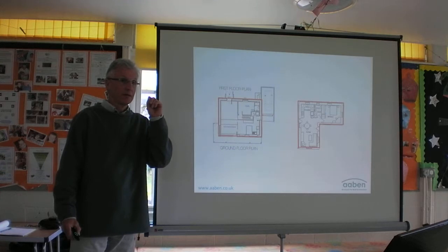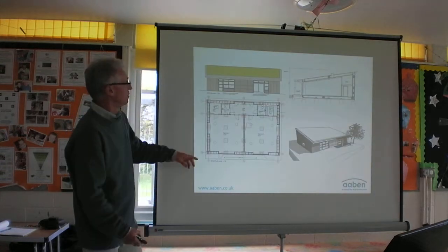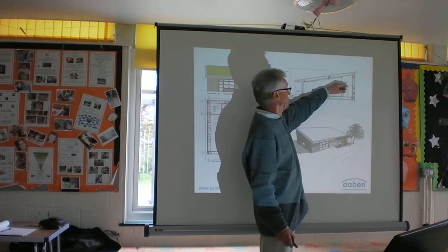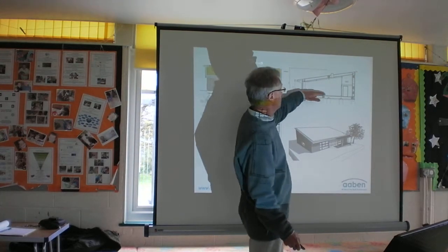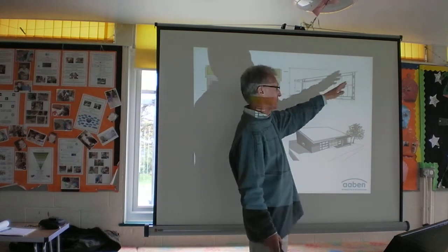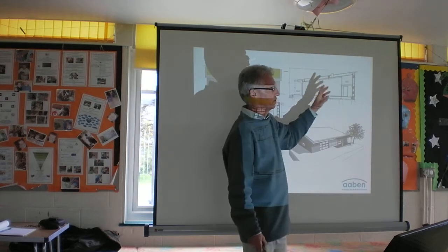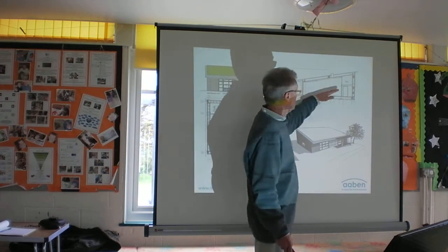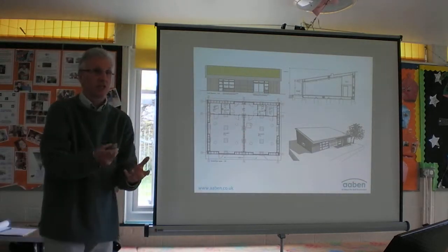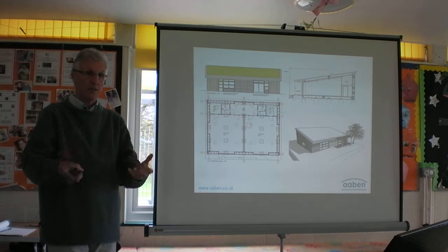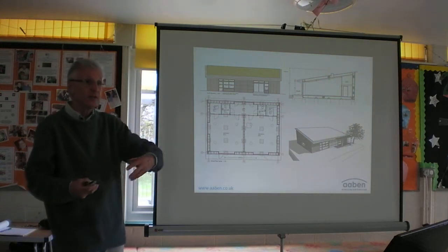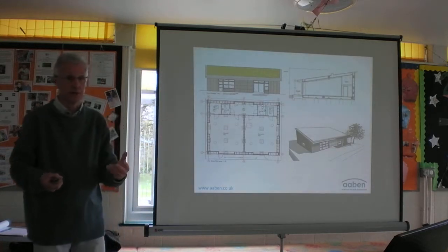This is high windows on the upside of the house, is that right? You're using the difference in air pressure here to drive it. You'll get 2 temperature things going on. You'll get a temperature differential, so you get stack effect, so warm air rises. You will also always get, unless there's absolutely still air outside, a pressure difference on the building, and air will move through it naturally. So you can combine the managed ventilation in a Passivhaus with some passive ventilation techniques. You can use natural ventilation techniques to cool the building in the summer.